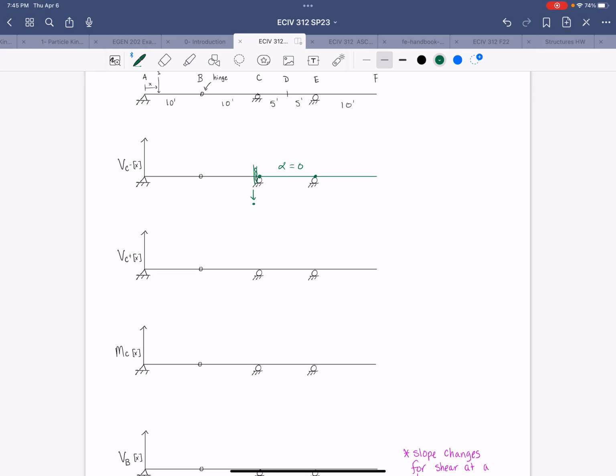We have to have the same slope on both sides of the cut. So from the hinge to the cut, we also have a 0 slope. All right, and this value is -1 because it has to be a unit displacement total. And then at the hinge, we can change the slope to meet the support condition at A. Now that influence line is all done, qualitative and quantitatively.